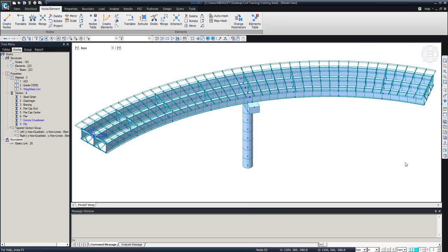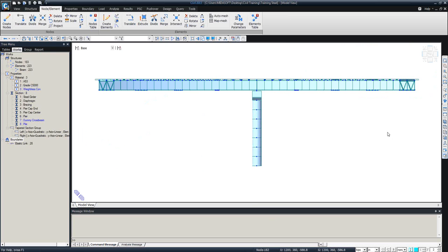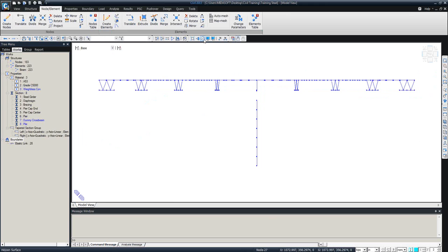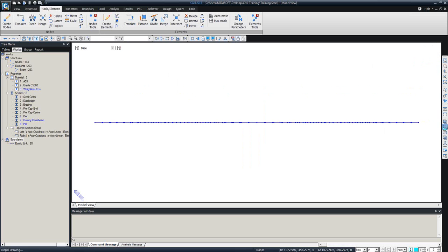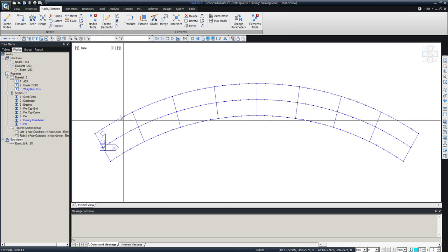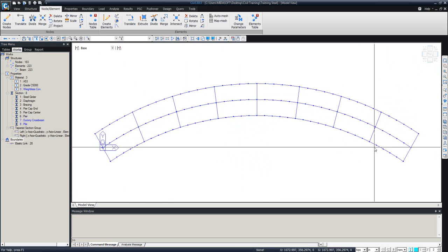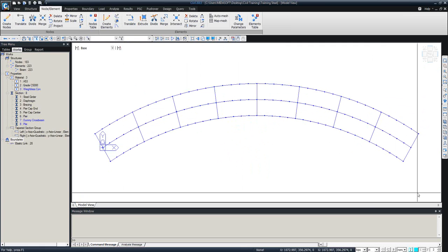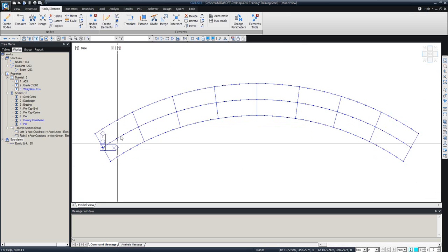See, here's the thing. If I turn this off and then just activate the top girder. What we see here is that most of the girders are left behind, and they are not connected to each other. So technically the girders are working kind of separately. But when we have the concrete on top of the girder, one of the roles of the concrete is to keep them all together working as one system, not as individual elements. So we have to simulate that.